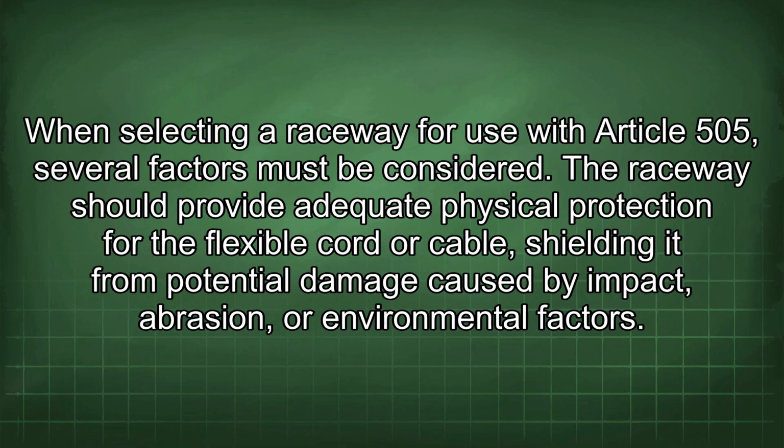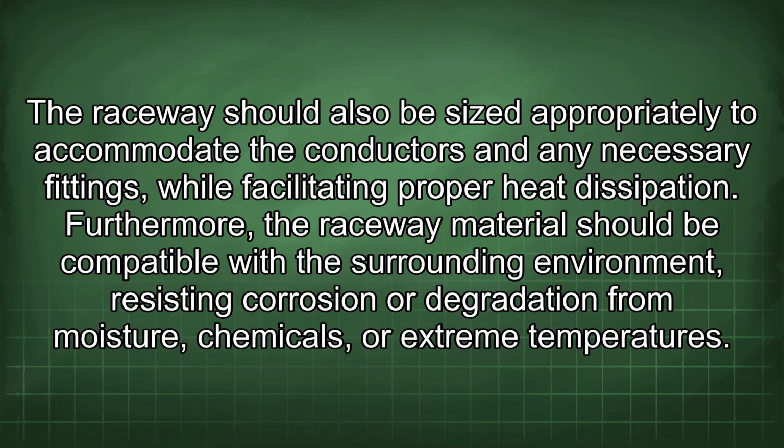When selecting a raceway for use with Article 505, several factors must be considered. The raceway should provide adequate physical protection for the flexible cord or cable, shielding it from potential damage caused by impact, abrasion, or environmental factors. The raceway should also be sized appropriately to accommodate the conductors and any necessary fittings while facilitating proper heat dissipation.